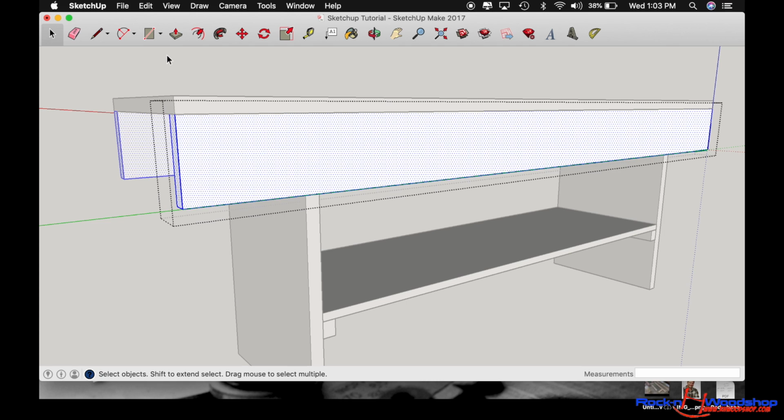So to cut it away, we're going to use our line tool, and you'll find that up here where the pencil is at. And you can do line, which is a straight line from point to point. And there's also freehand. Now, if you want to get fancy, go ahead and do freehand, but I don't recommend it unless you're really good. So we'll do just a straight line. Now, I want to hover over that particular point where it starts, and I want to draw 45 degrees.